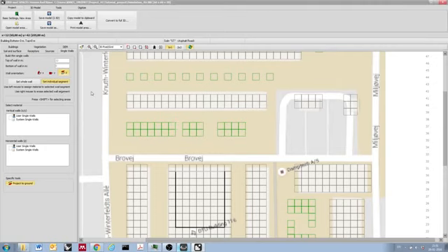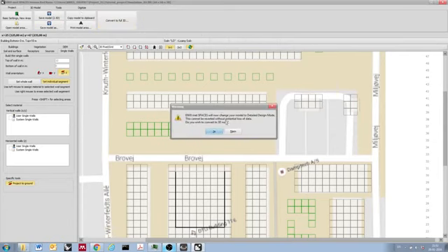Walls is a two-dimensional object in this 3D system, and usually we don't want to use this, so I don't want to go into that now. Alright, save our project, save model. You can save it as something. I have already saved it as simulation 02 Inex, and let's just save it here. We can now convert this to 3D, and it will prompt that you might lose some data if you do this, so be sure you have saved the model.